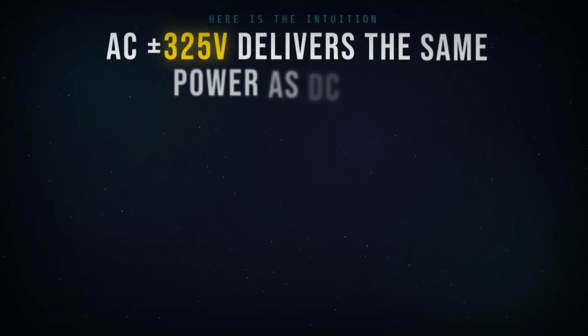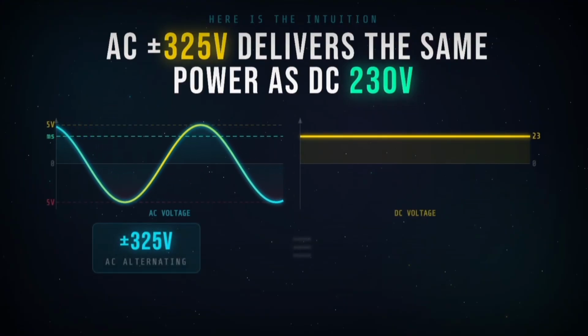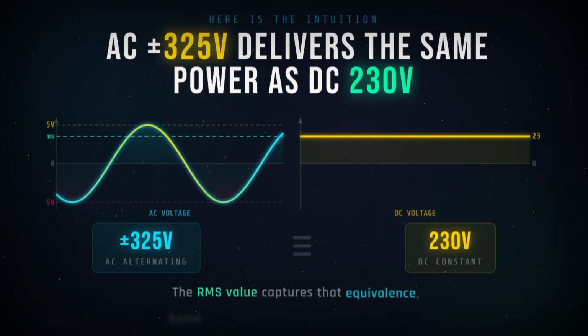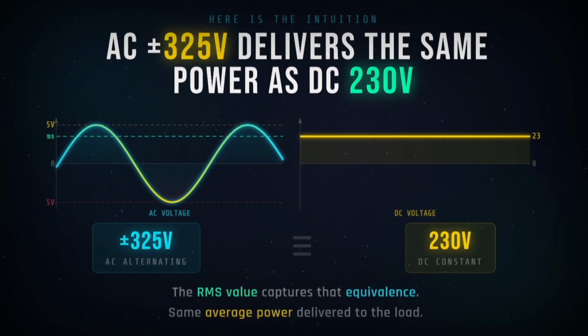Here's the intuition. An AC voltage that alternates between plus 325 volts and minus 325 volts delivers the same average power as a 230-volt DC source would. The RMS value captures that equivalence. The mathematics gives us a clean formula.